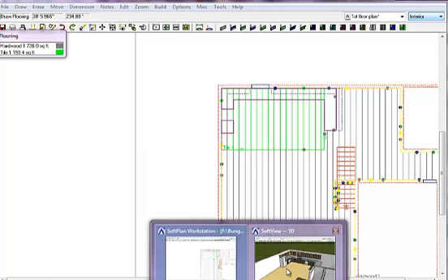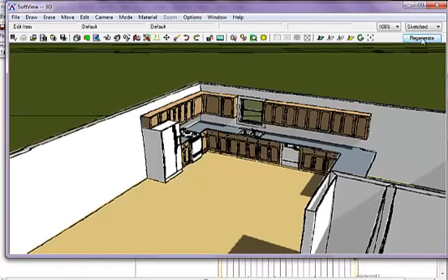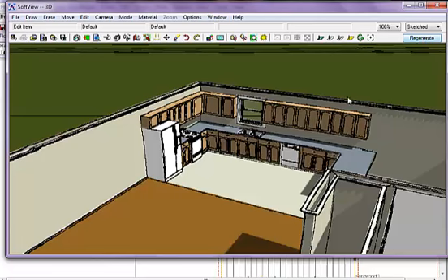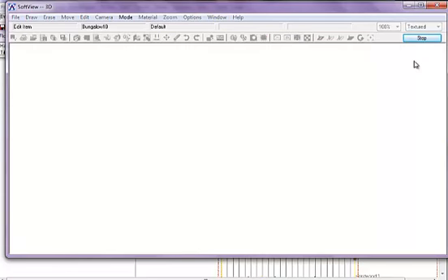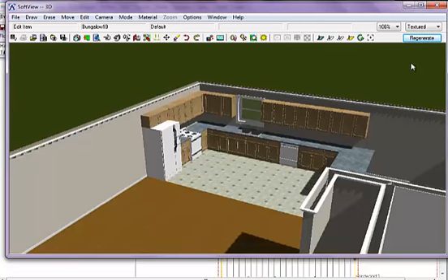So I'm going to go to the build. I'm going to regenerate this. If I regenerate it in sketch mode, it's not really going to show me much. So now you need to go to either textured or rendered. Rendered can take quite a while. You're probably also going to want to work just in the quick build rather than the full build when you're doing this kind of stuff, so that it doesn't take as long to render your drawings or to set them as textured.